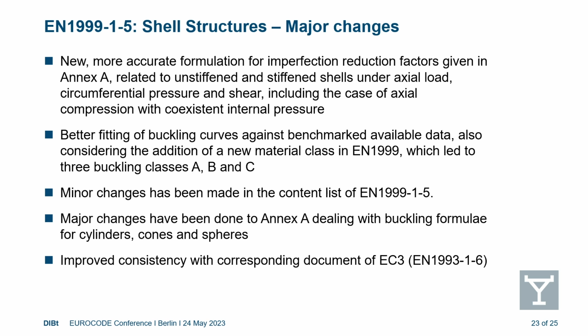As you know, shell structures are very sensitive to both geometrical and mechanical imperfections. And in the case of aluminium, these imperfections interact strictly with the plastic behavior typical of the material. That's the reason why special work was done on this aspect, leading to a new formulation of buckling curves and imperfection reduction factor. So the curves were refined based on the available data.